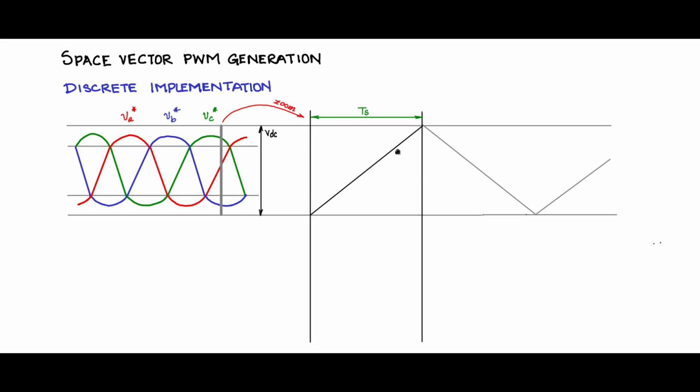So you see, because of this triangular, this linear conversion, the voltage can be converted to time because of this linear portion of your triangular waveform. Now we will mark the intersection points. There is an intersection point for C, which is at the maximum now, there is an intersection point here for the VA waveform, and one here for the VB waveform.